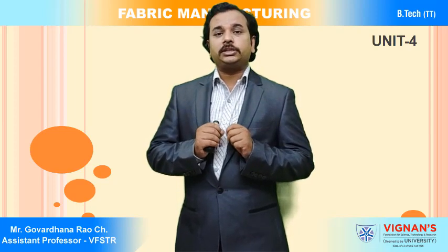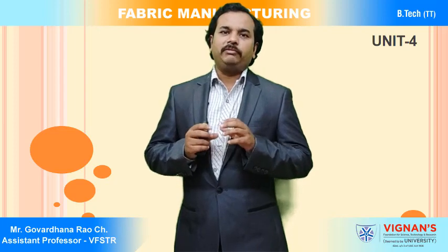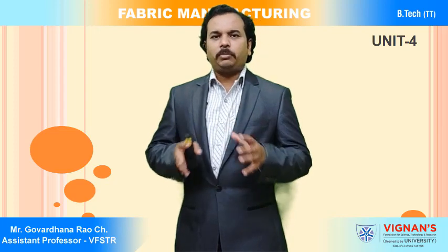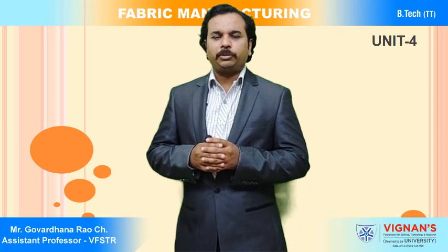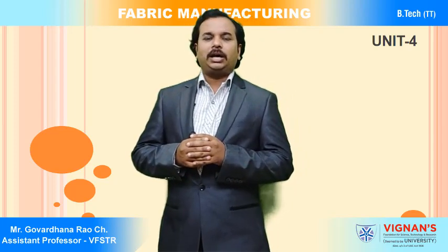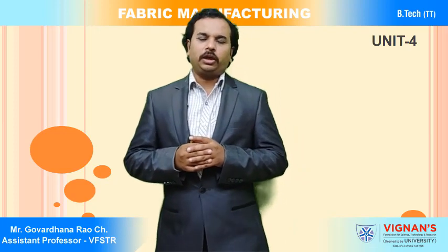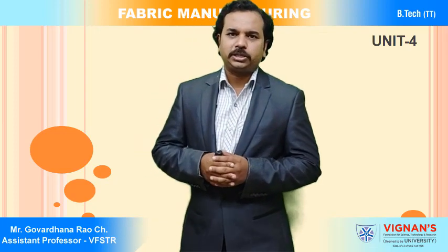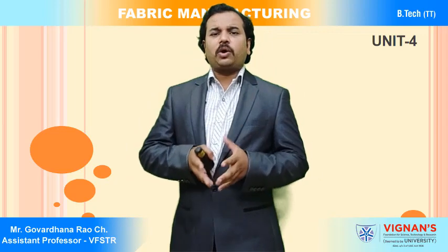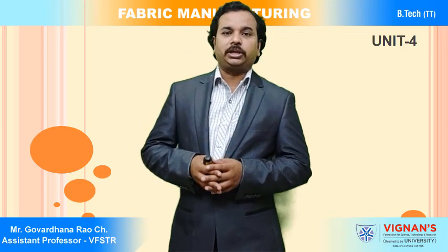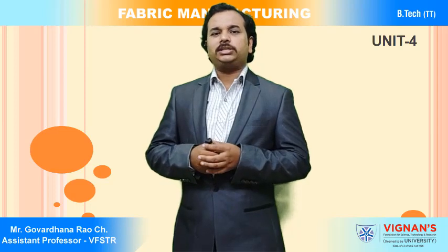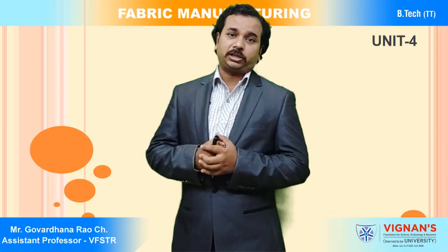Individual ends are knotted together at the weaving zone. There is a small machine called the knotting machine, which can knot the old running ends and the new ends. So these are the post sizing operations we have discussed. After the drawing-in and denting operations are complete, we send the beam to the weaving machine. So we have discussed what exactly shuttle weaving technology is.